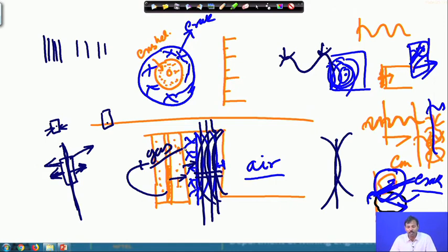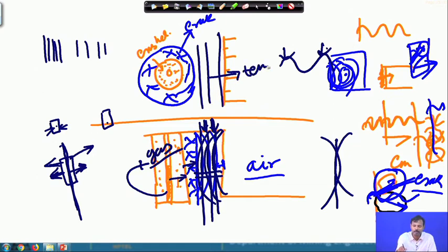So, our objective is this: because there is a time gap between the shock energy release and the gas energy release, what we want is that, before the gas formed reaches the cracked position, our tensile failure, which is called tensile slabbing, must be completed ahead of the gas reaching this position.